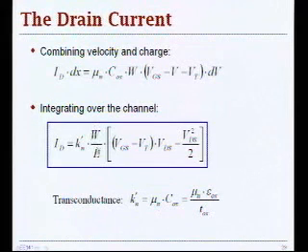And you can see that when you have a very short channel, then you have high current, which means speed. And analog designers do a lot of interesting things with channel length, but in digital gates, in majority of cases, we will use only minimum channel length, because that device gives us minimum gate capacitance and also gives us a lot of current, because you're interested in speed and compaction.